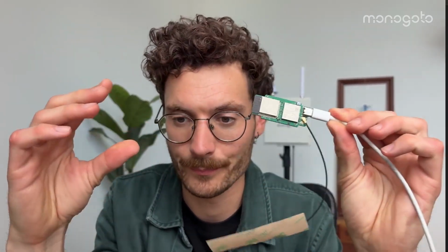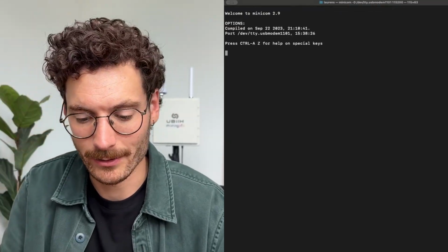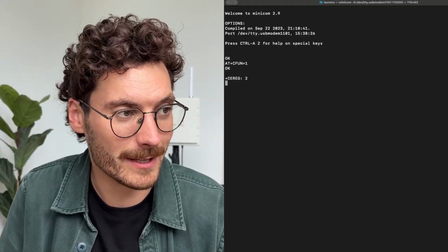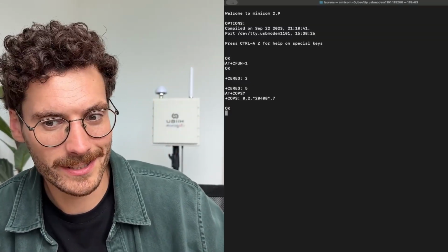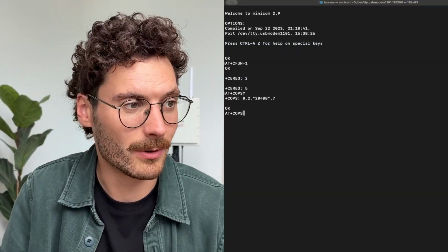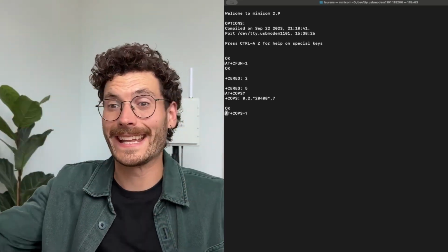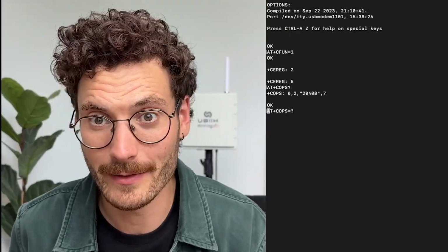Now let's try to connect an IoT device. I'm using the Walter board, my dev kit, and I'm going to connect directly to my computer. Then I'm opening up the serial monitor, allowing me to send AT commands directly to this device. First, I need to turn the radio on. And I see that it's connected as of now, but it's not connected just yet to this private network. So I'm going to conduct a full network scan. The device scans all networks around and hopefully it sees this private network as well. So let's give it a minute.